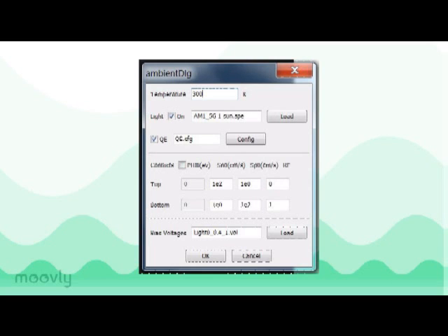We will keep our contact parameters constant such that we ignore the barrier heights at the contacts by leaving this box unchecked. Then we will consider surface recombination velocities to be on the order of 100 for majority carriers and on the order of 1 for minority carriers. RF is the reflection coefficient. At the front surface, we will leave it at 0, and at the back surface, we will leave it at 1. This assumes that none of the light is reflected out of the cell, and that any light that reaches the back surface will be reflected back into the material.